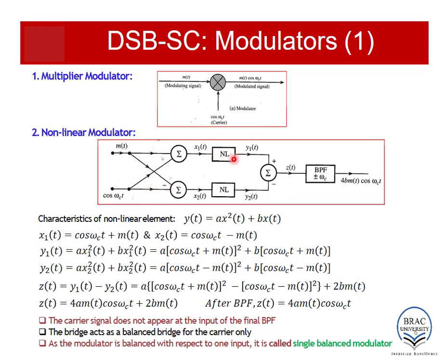Then comes the non-linear blocks. The non-linear blocks simply introduce non-linearity in the signal. That means previously we were dealing with xt, now we will deal with a non-linear equation of xt. The characteristics of a non-linear element can be anything. In our non-linear modulator circuit, the particular non-linear block we are using